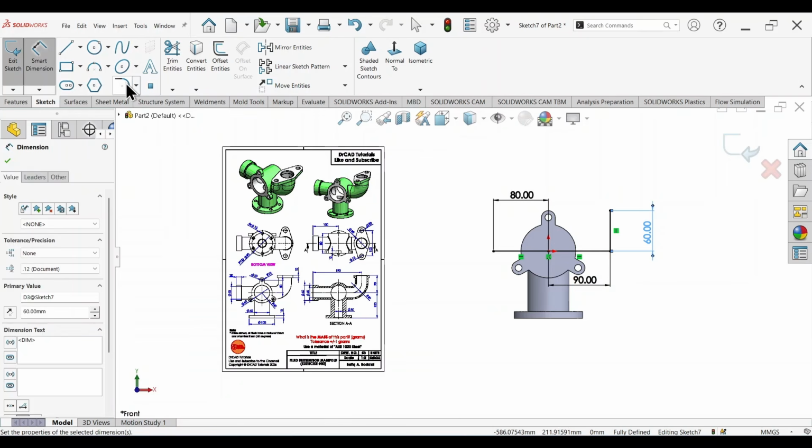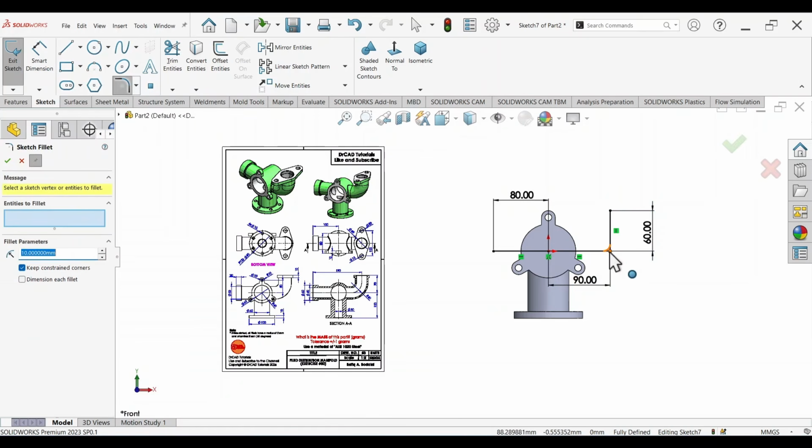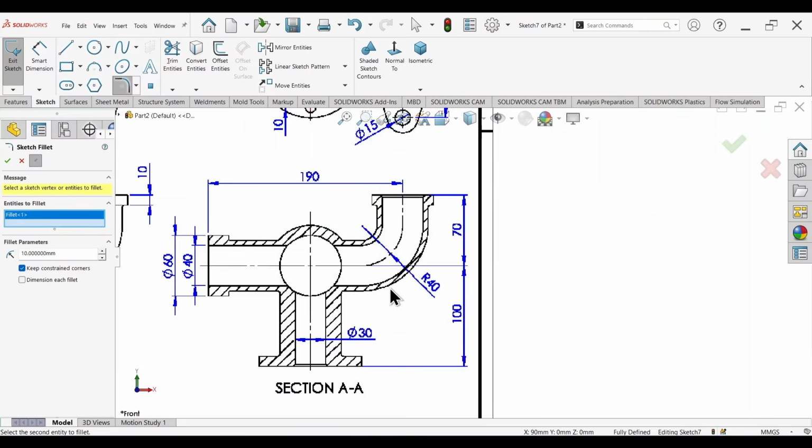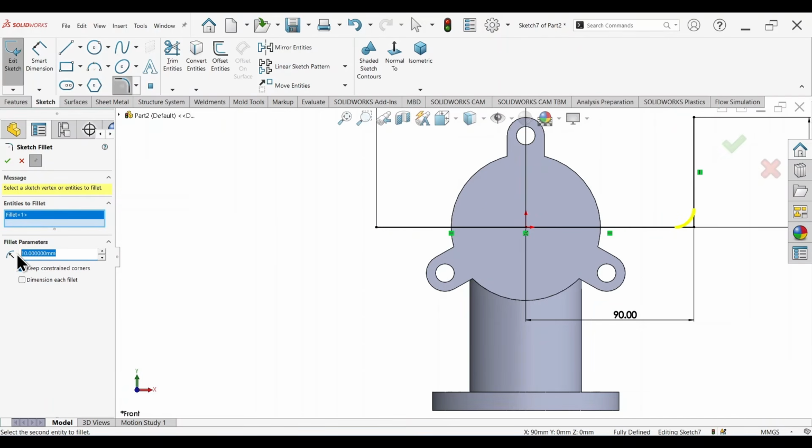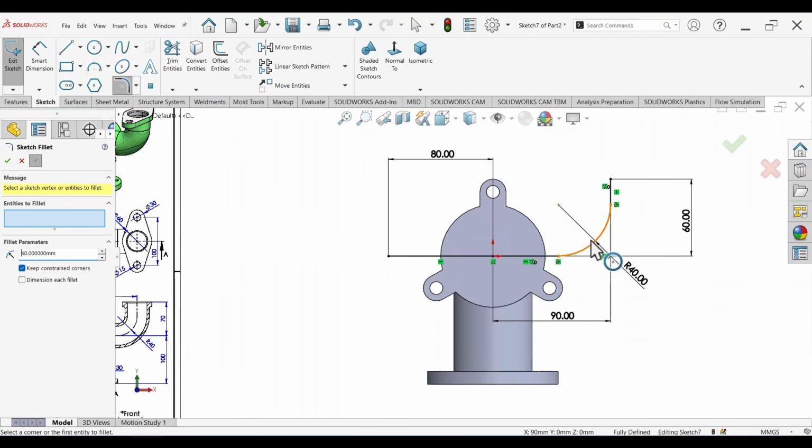All right. Select the fillet tool, and we're going to assign a fillet radius for this edge. We're going to set the fillet radius as 40 millimeters. So assign a fillet radius of 40. Okay, so that creates the path for the 3D swept boss base tool. Click OK.